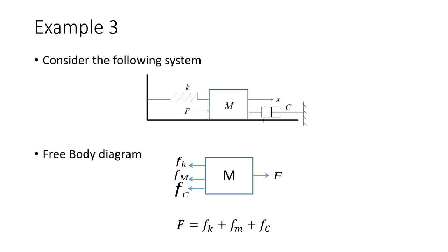Okay, this is another system. So we added one more term now. Before we just had the spring and the applied force. And so here now we have a damper also. So it is also damping. So we have three of them acting now: the spring force, the Newton's force, and the damping force, equal to the total force. Our output is x. Our input is this F. So we can write the equation as we wrote it before.